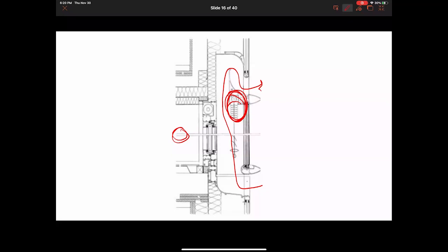Now we have a few options. We can put exterior shades, and those can be really beautiful, but they require a ridiculous amount of maintenance, and they often break. Because they're outside, they're often thin members, so they warp. You can maybe find some examples online, or maybe where you live. Beginning around 2007, and maybe peaking in 2017, I'll say, but it's still around a lot, are buildings that have these wood screens with thin horizontal wood slats.